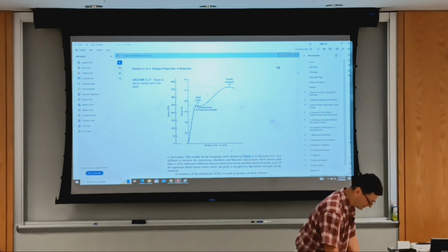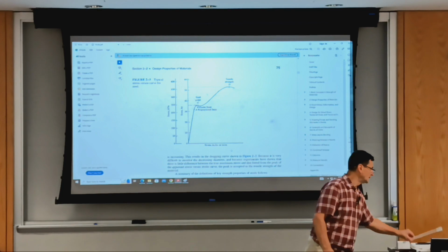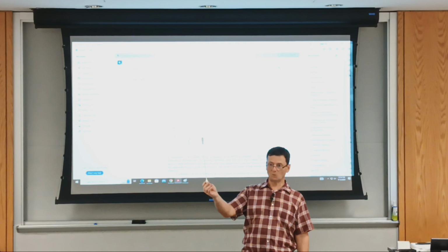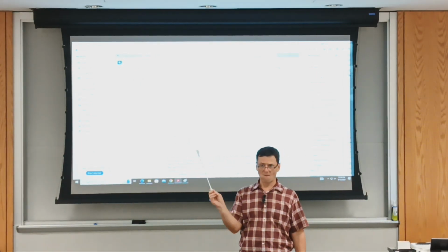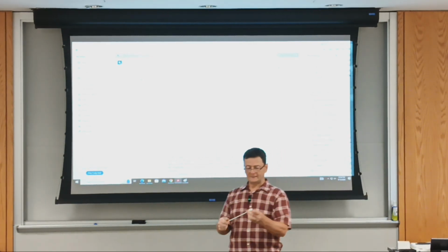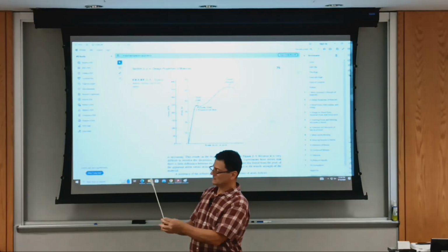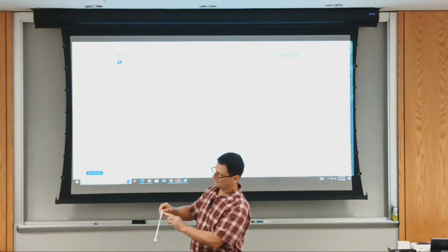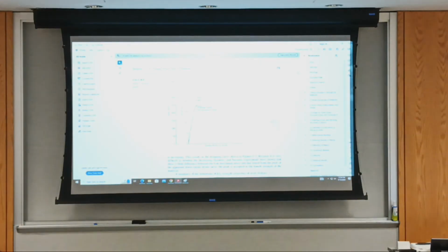For any plastic forming, you'd like the ductility to be as high as possible. Look at the specimen. This was some plastic material, probably polyethylene. Look at how much it stretched before it probably even reached the travel of the tensile equipment. So this is called superplastic material. And also, although it's not material science, look at the appearance. It looks stiffer and more dense than the original material was. Likewise with steel material.